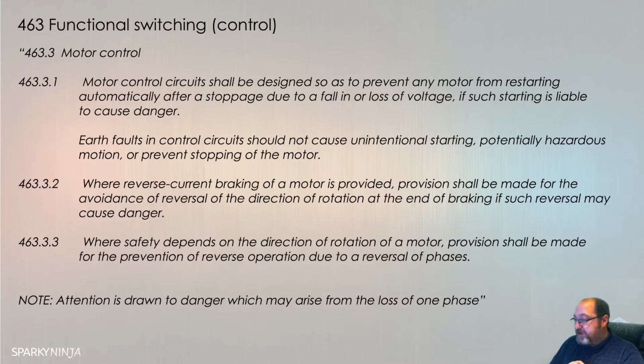Where safety depends on the directional rotation of a motor, provision shall be made for the prevention of reverse operation due to reverse of phases. Okay.